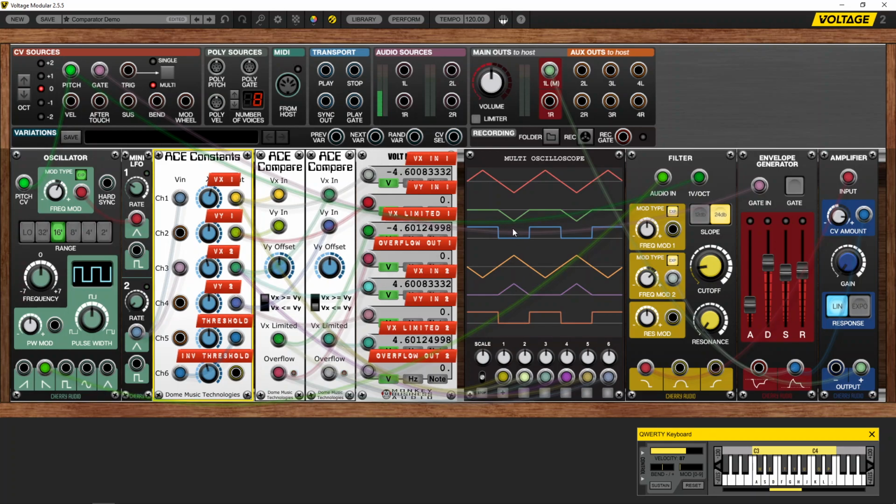What you want to happen is that you get the positive voltage for this part on this comparator and the positive voltage coming out on this comparator. So what we'll have to do is, we could do one of two things. We could either change the condition on the second comparator, but what you've got here is two negative going cycles. So if you want it going positive, we'll change both conditions here.